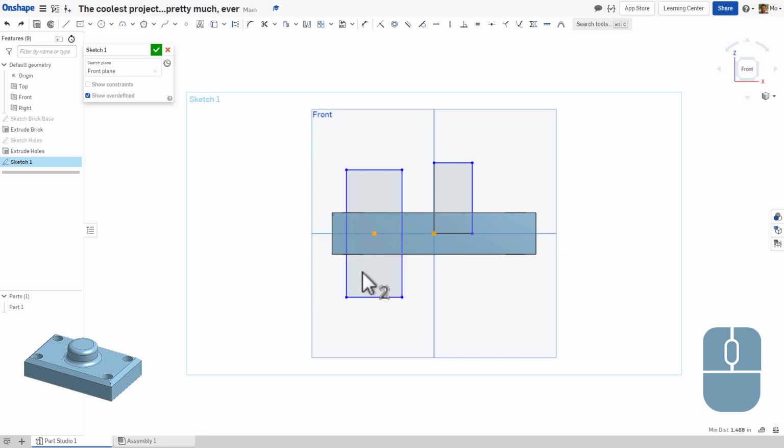So, this is to say that every click counts. When you're using CAD, you need to be very careful about where you place your things, anything, be they dimension bubbles or corners or points on a rectangle, right? Every click counts. If you see these little inferred constraint bubbles pop up, that means that you're going to be locked in there if you place your rectangle here.